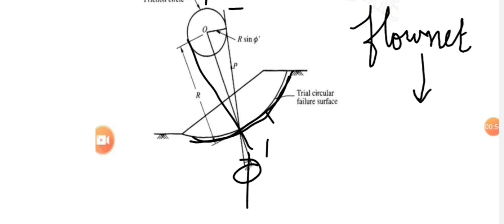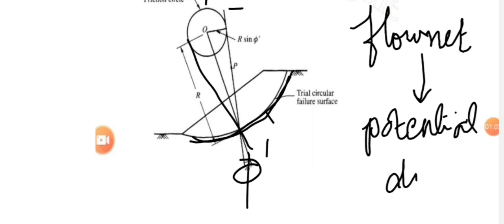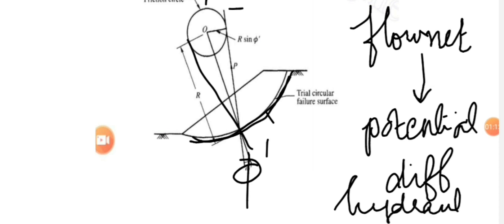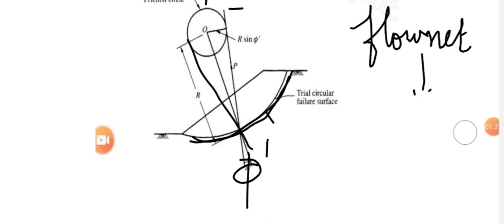That is, this flow net diagram will give you the potential difference along which water will flow, that is hydraulic gradient, and thereby pore water pressure. Now we are least concerned about that. With respect to geotech, it is actually coming under hydraulic section. We have to consider that force also. Then intergranular pressure, that also acts along the boundary. So these are the forces we have to consider. Since it is rotational failure, I am introducing a new factor of safety, that with respect to overturning.